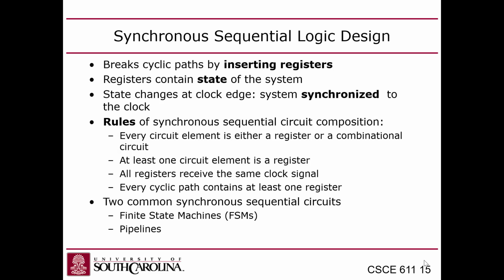And then every cyclic path contains at least one register. So you don't want to have cycles in your logic circuit unless the cycle is broken by a register.